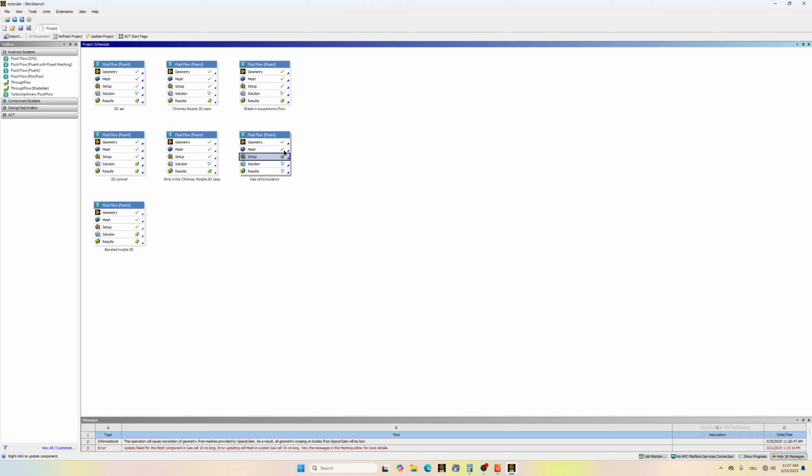It shows checked, but when you try to import in Fluent, you'll get an error, and it doesn't say why. So if you get that error, most probably is because of the mesh. So go back and remesh it using Cartesian meshing, or changing whatever the geometry, changing the way you mesh it and so on. Mesh size.